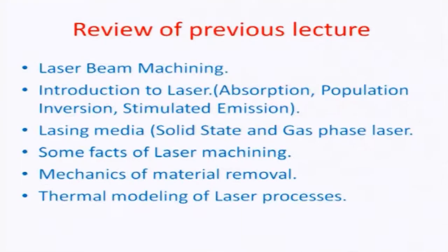Let's recap quickly what we did last lecture. We talked about laser beam machining. As we probably already know, it's basically the photon to matter interaction, which essentially converts into the physics of photon to phonon conversion, and so there are lattice vibrations induced by the high level of energy pumped in by the photons, which causes a local temperature rise, and it's a surface phenomenon.